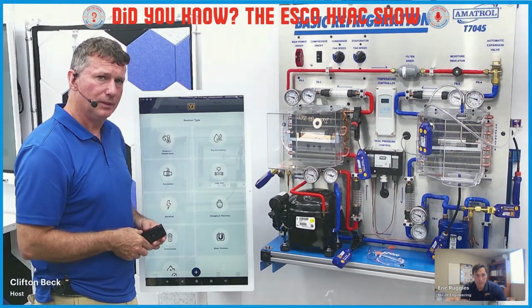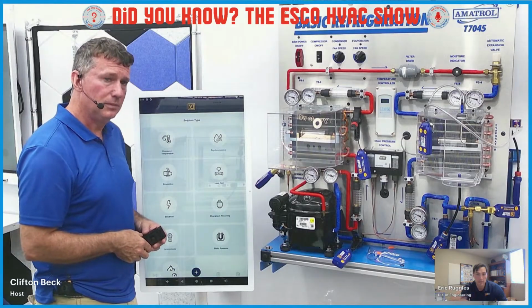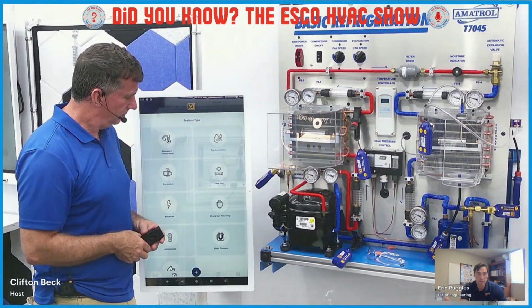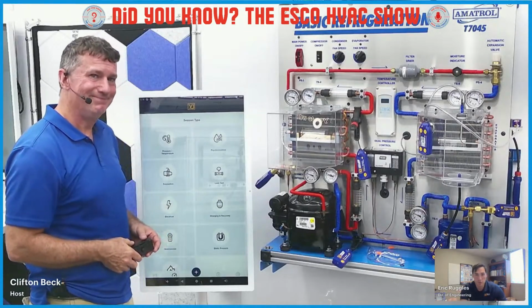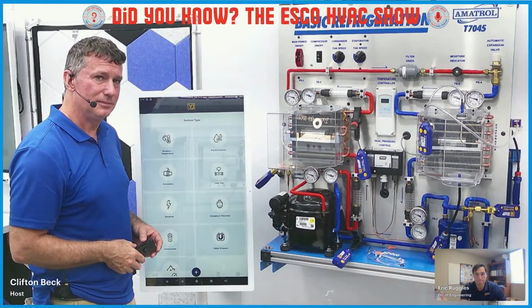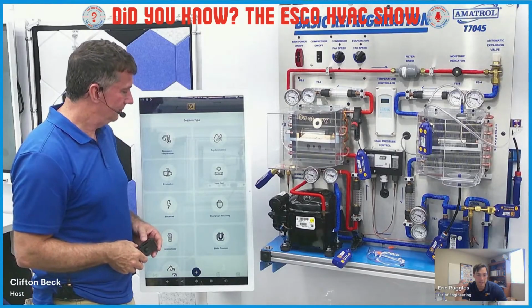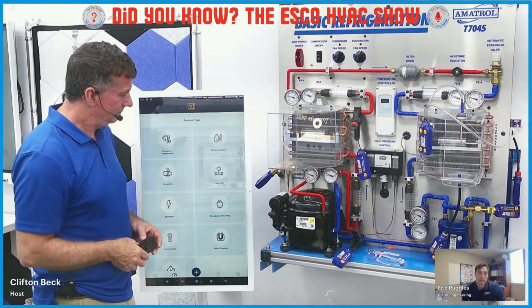Same thing for the leak test. That would typically be a nitrogen pressured leak test. And you can either use temperature compensation or not. So if you have a pressure sensor and a temperature sensor, you can use both of those on the system, and it'll do the full test for you as well, picking what your acceptance level is of leak or pressure change.